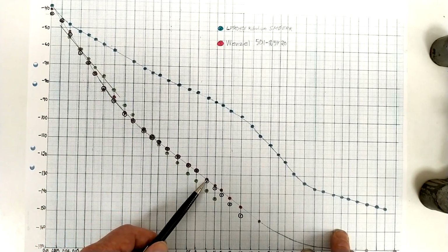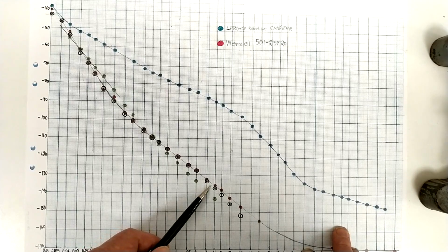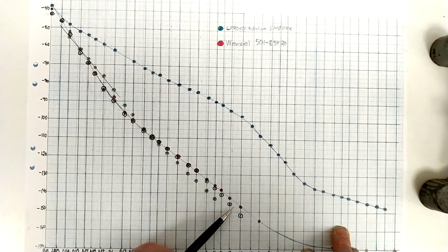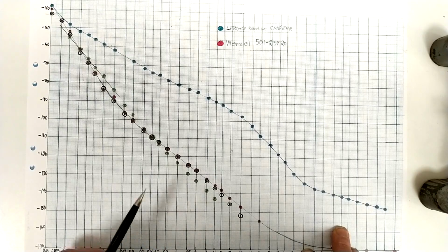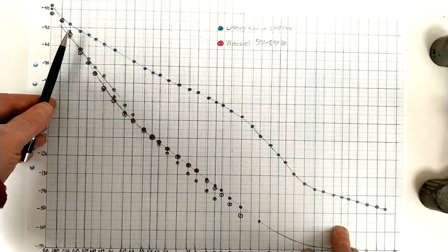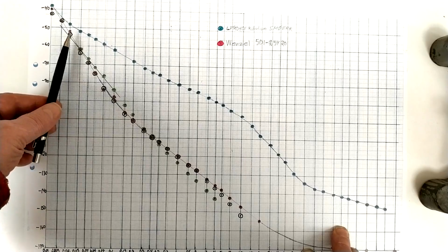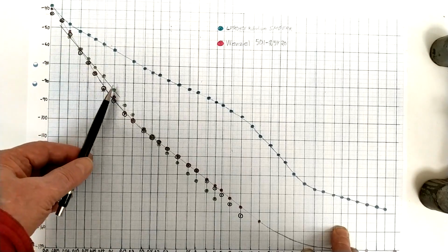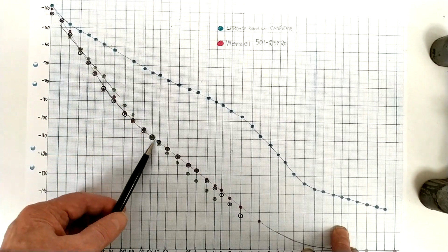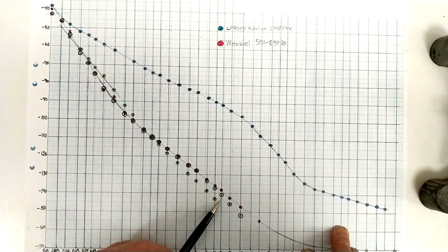and then when we come at about 3 Hertz, then the filter characteristic of the crystal starts to improve and filter out some of the noise from the Wenzel. And the cause of the peculiar shape is I was measuring the difference between those black circles and these green marks, which are my oscillator when it's running as an oscillator.